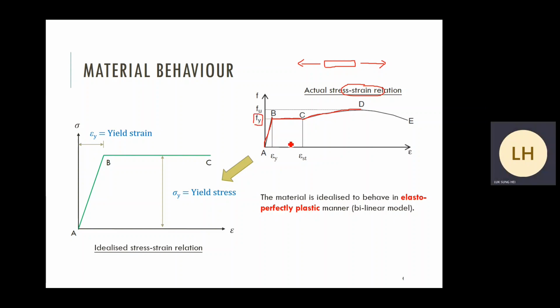Y denote the yield. And then up to the level D. You can see that point D is the actual maximum stress that the member can suffer, that the material can suffer. Beyond point D, the material enters the softening stage. Stress decreases. That means they cannot take too much loading.